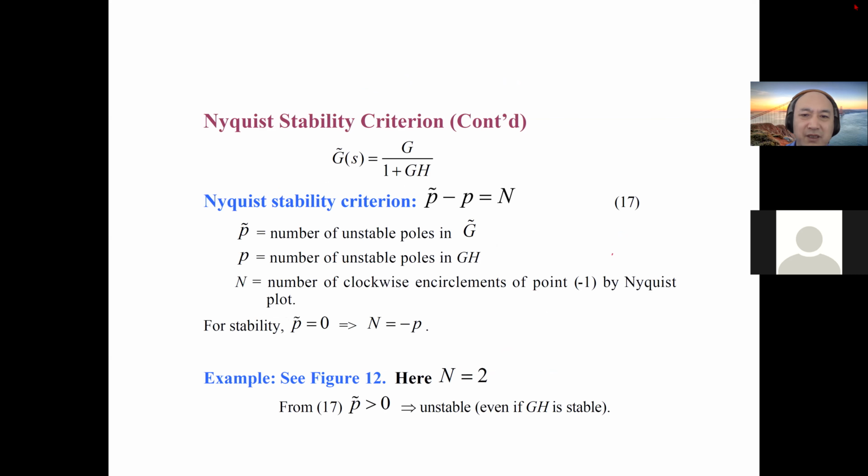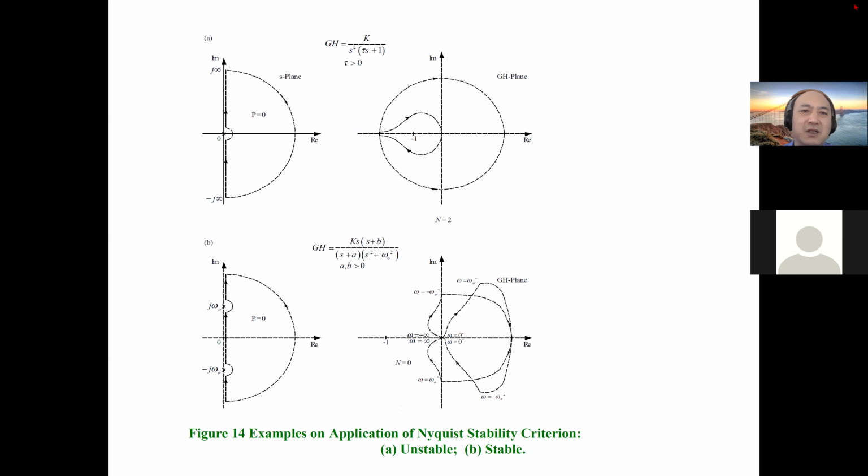So the Nyquist stability theorem is an abstract setting, but you only need to remember what I just told you about the encircling problem. This is called the critical point, -1 + j0. This is the number of unstable poles, and they have a relationship like that. It's hard to memorize, so let's just use the encircle problem, okay?